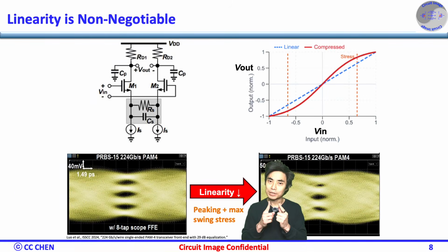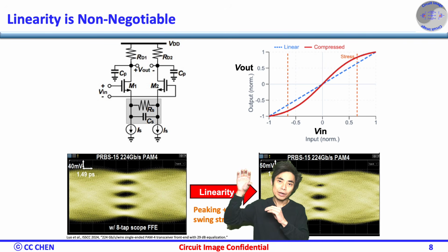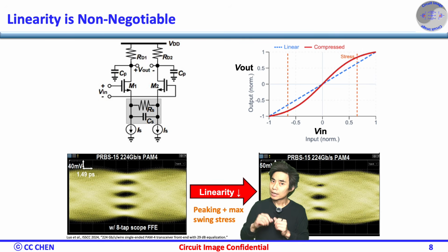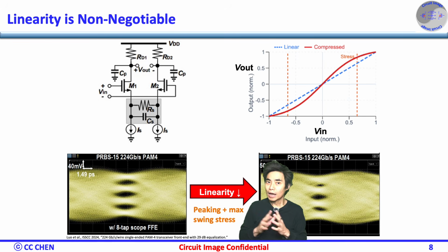With the CTLE frozen, distortion cannot be corrected later. Noise can sometimes be averaged. Distortion cannot. If high-frequency boost pushes the outer PAM4 level into compression, you permanently degrade SNDR. So design headroom for the worst-case input amplitude combined with worst-case peaking. Frozen CTLE means linearity is not negotiable.